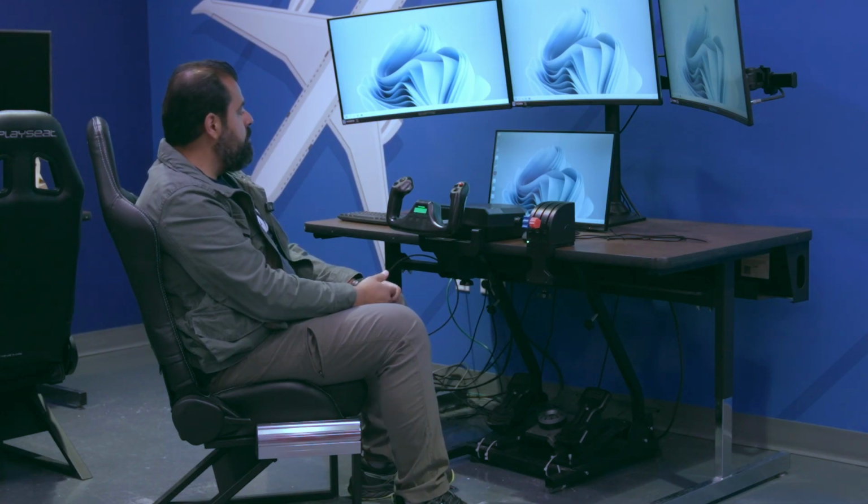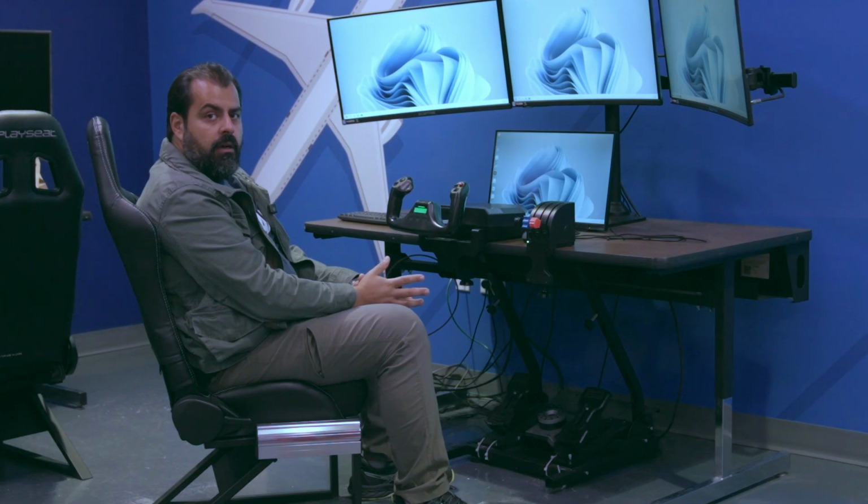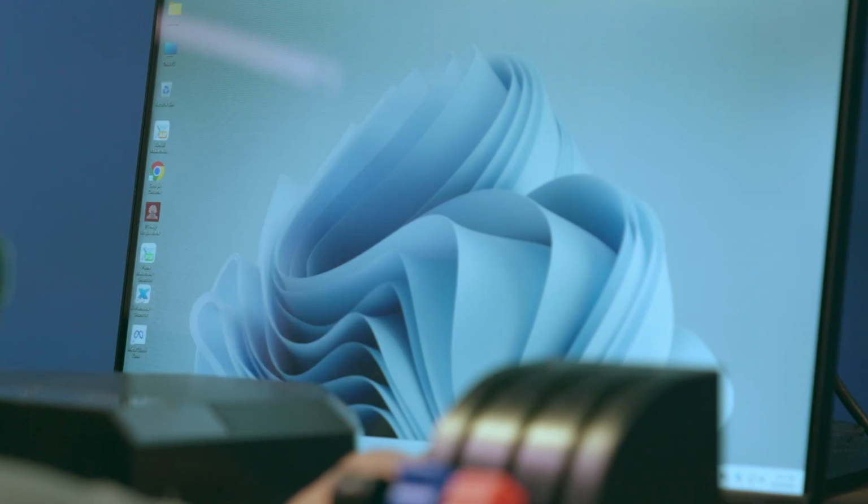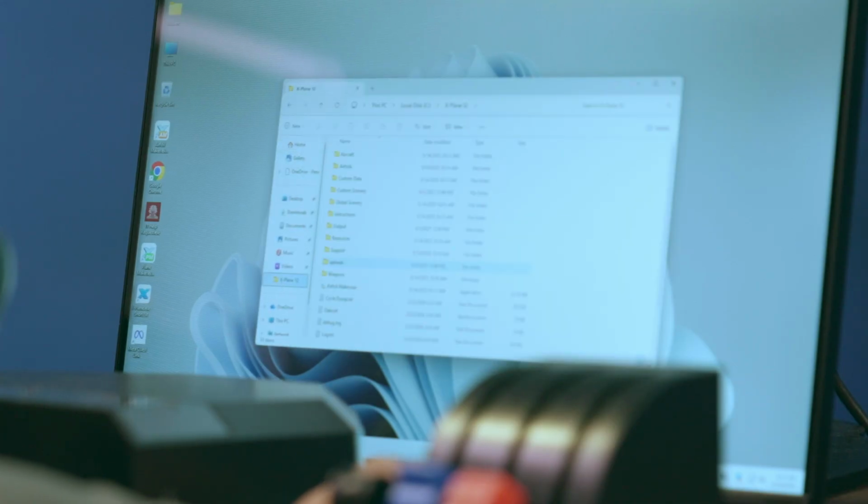The next step would be to start the software and run the simulation. The software of interest for us is called X-Plane. It's right here. And the CAD software we're going to use later to modify the aircraft is called PlaneMaker. It is also right here. Most of these should be on your desktop, but if not, you can just go to the Windows search and look for them. The address is in the C drive, which is where our aircraft repository is also located: C drive, X-Plane 12.